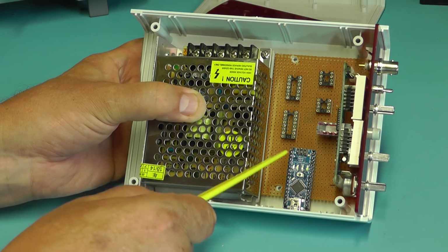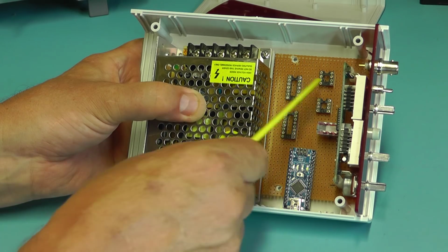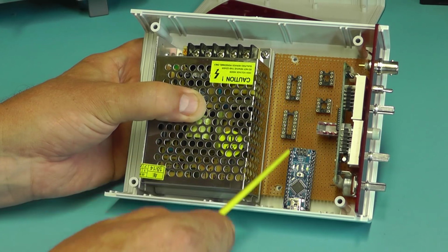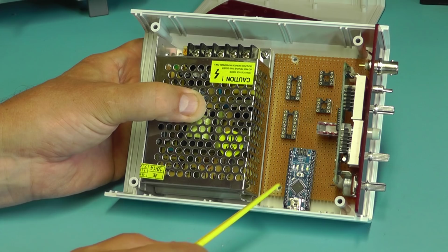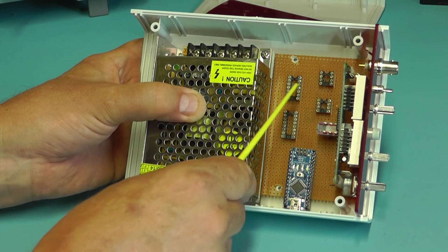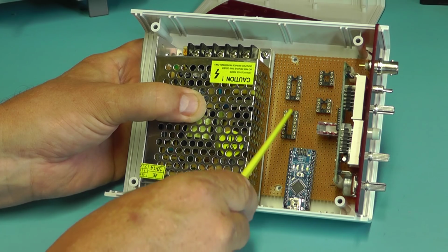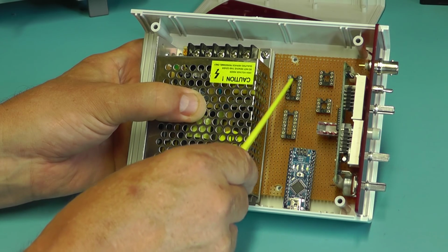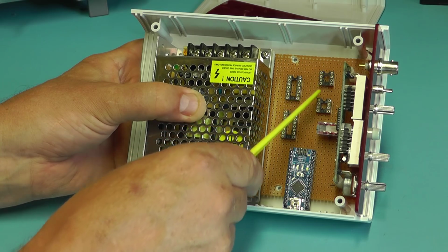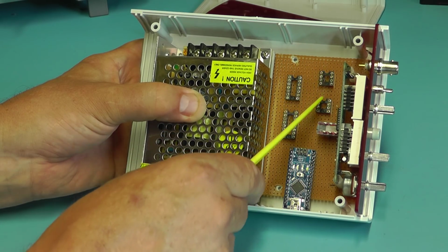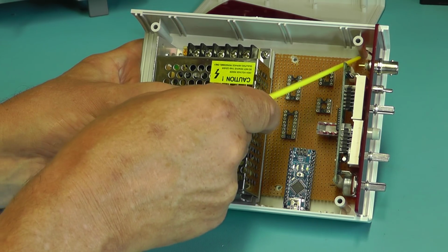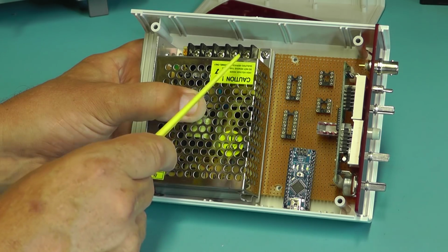and to do that I've had to rethink the layout of the other components on the matrix board. So what I've done here, you can see I'm considering putting the function generator IC probably around there, the Schmitt trigger IC there, and then the 2 op amps for the output stage there, which is near the output BNC socket on the front panel.